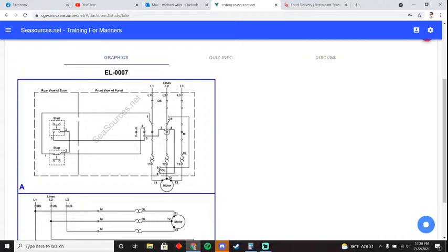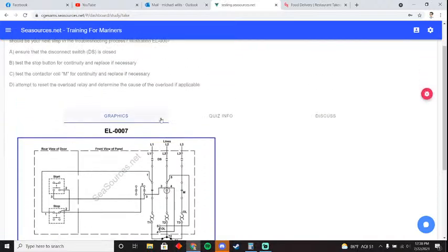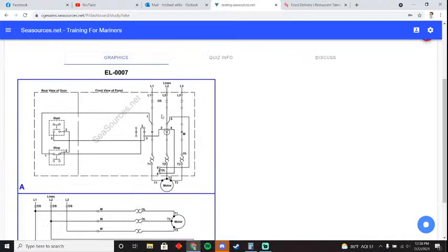So you're getting 120 or 440 or 210. Something's wrong down here. So you're tracing this. There's T3, which is lead 3 of the motor. And you're looking at that, and you're looking at that, right?